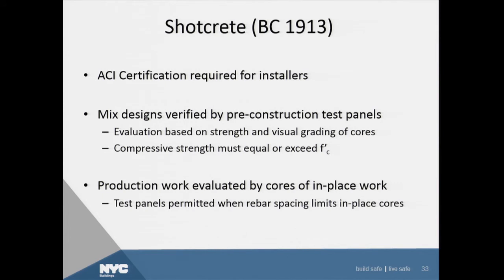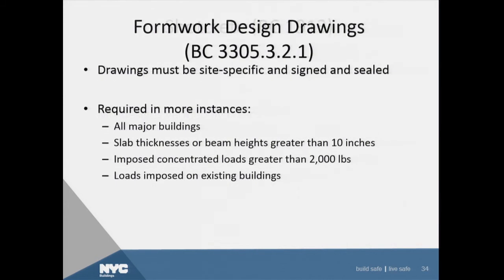I've been told here I need to speed up greatly, so I'm going to do that right now. There are new requirements for Shotcrete, including certified Shotcrete installers be used when Shotcrete is used for concrete installation. The formwork design requirements in Chapter 33 have been expanded here. Formwork design is the instances where formwork design drawings are going to be required to be provided by the contractor. Signed and sealed drawings provided by the contractor, someone working for the contractor, have been expanded in Chapter 33 to basically encompass many more instances than what was previously required.